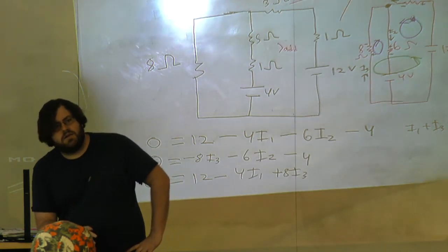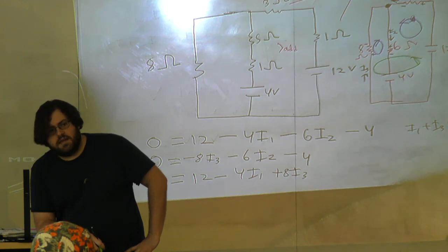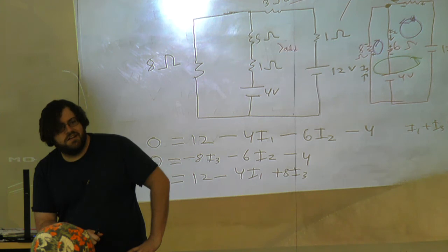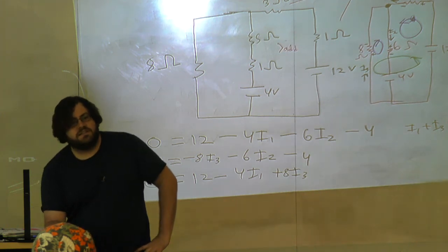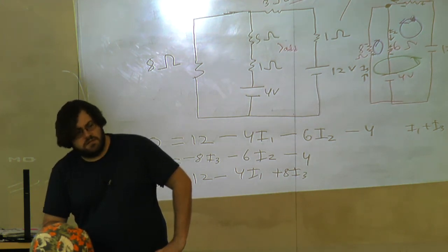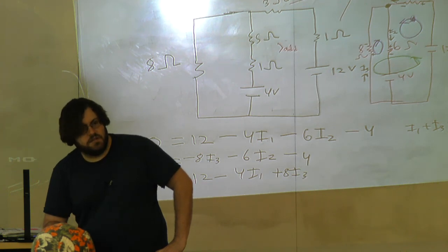No, it's not a clockwise counterclockwise thing. So the fun part about Kirchoff's laws is that I can draw my circles wrong and it'll still work, right? Because we don't know necessarily which way the current is going, so we kind of have to guess. And if we get a negative number, then we drew it backwards and we switch the sign and we're done.